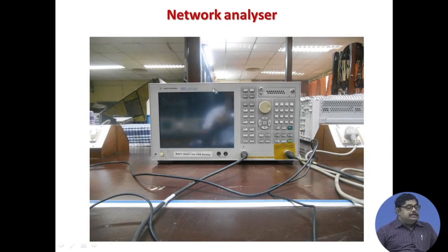So, you can measure S parameters. Now, this is the network analyzer that can measure the S parameters. These are available in 2 port, 4 port, etc. Obviously, 4 port is quite costly. A network analyzer is quite costly equipment, but nowadays its price is coming down. In the 80s it was invented, and nowadays in your lab you can hopefully see a network analyzer.